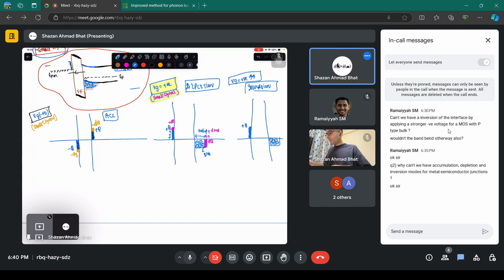With a little more charge because of the small signal, this is now the overall depletion width. It does not go beyond that because you cannot have unlimited depletion charges in a system. Once it reaches the maximum depletion width, W_d max, at the threshold voltage, it does not go beyond that. You cannot uncover more negative charges now. Whatever you wanted to uncover, you have uncovered.